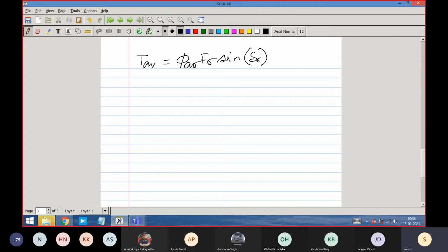How is this getting related to the mechanical thing? Because if I just produce a torque and there is no load, then the machine will continuously accelerate, isn't it? The fundamental law of mechanical energy is J d omega mechanical by dt is equal to T E average minus T M. M is the mechanical load, isn't it? There has to be ultimately a balance. Otherwise, the speed of the rotor will always increase. We have developed a torque, but there should be a counteracting torque also. Otherwise, how does the machine come to a constant speed? In order to come to a constant speed, d omega m by dt has to be 0 under steady state.